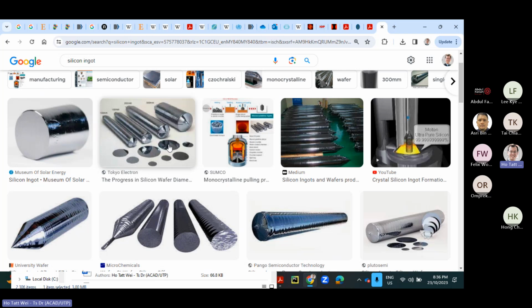That's why they look like mirrors, right? And they're kept in a very pure, clean environment, like no hands touching this. All is done by robotic handlers, which are very clean. Even these wafers are in clean rooms where they measure the quantity of dust, like 100 ppm, 100 parts per million, and so on, right? Because if you have one dust land on the silicon wafer, that's enough to short or to kill a bunch of transistors and things like that. So the fabrication is done in a clean room, in a very clean situation, and you start with silicon wafers. So you have all of this.